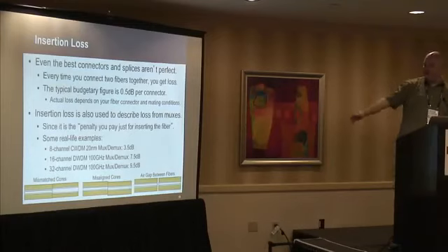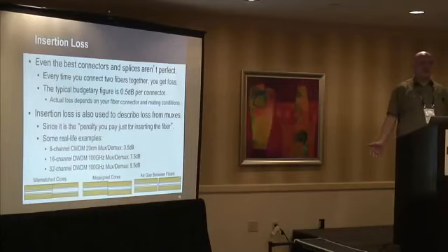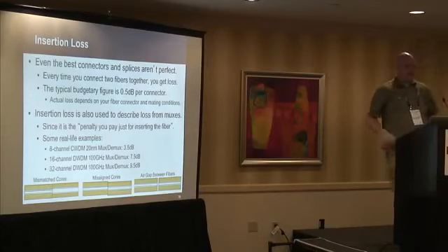And here you can see 3 different types of insertion losses that you see when connecting cables. One, mismatched core size, which we talked about before, but it can actually happen even between single mode fiber. Some fibers will be 8 microns, some will be 9. If there's any type of difference, you'll have mismatched cores. You can have misaligned cores where the things don't quite meet up perfectly, and you can have an air gap between the fibers. You just don't fully insert the fiber. It'll still work, but you've got that air in the middle, and it'll start to lose a lot of signal.